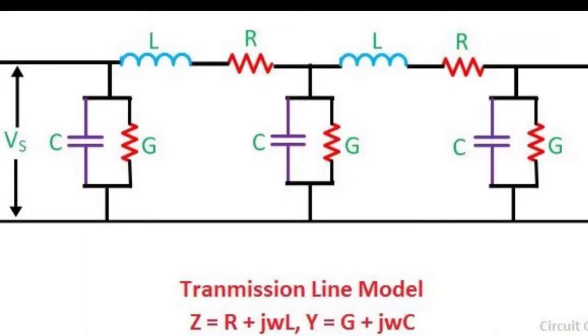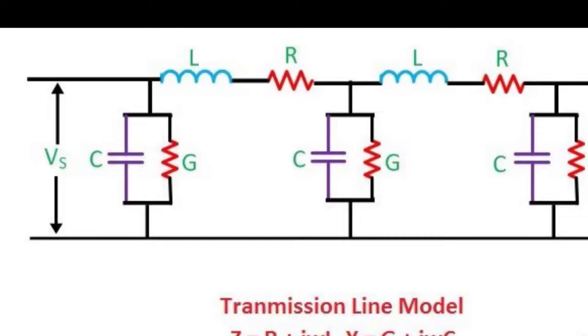In shunt conductance, air acts as a dielectric medium between the conductors. When an alternating voltage is applied to the conductor, some current flows in the dielectric medium because of dielectric imperfections. Such current is called leakage current. Leakage current depends on atmospheric conditions and pollution like moisture and surface deposits. Shunt conductance is defined as the flow of leakage current between the conductors. It is distributed uniformly along the whole length of the line, is represented by the symbol Y, and is measured in Siemens.